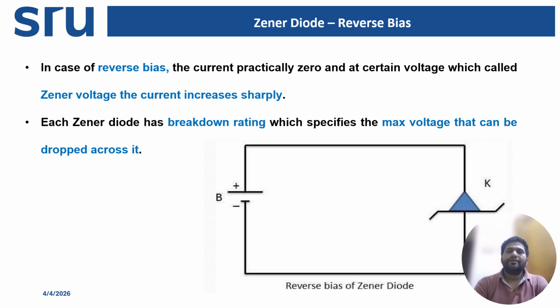So what is breakdown? When the reverse voltage is small, only a teeny reverse current flows, and the diode behaves like an open circuit, but the output voltage increases with the input voltage. So no regulation occurs in this region before operation at breakdown voltage.